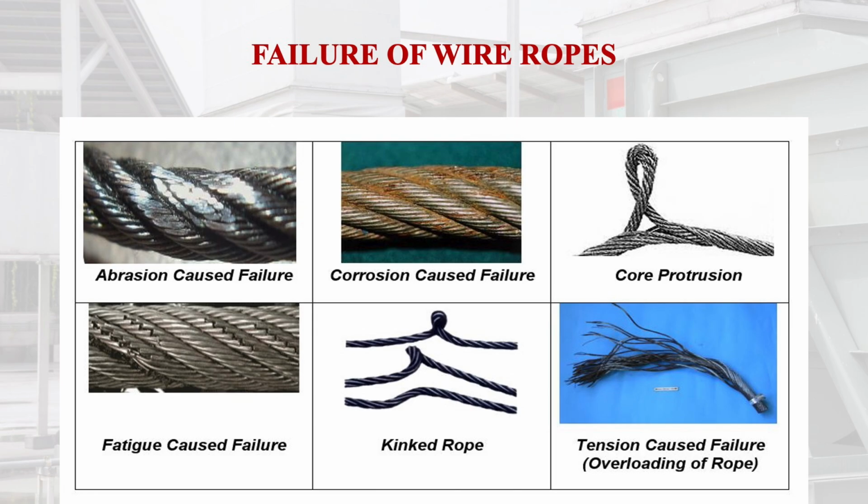If they are too high or some wires are already coming out of the strand, then these wires should be changed. Next is the core protrusion. This is nothing but some wire being overstretched and the core protruding.